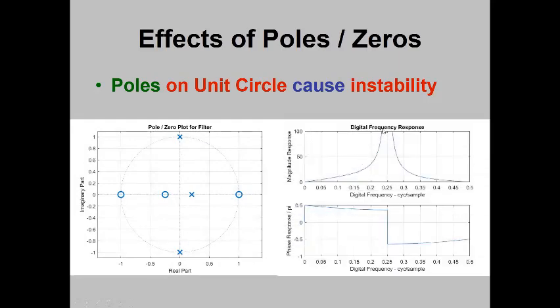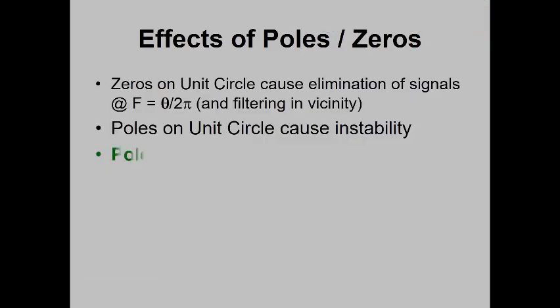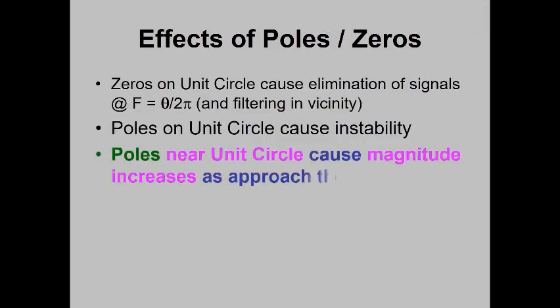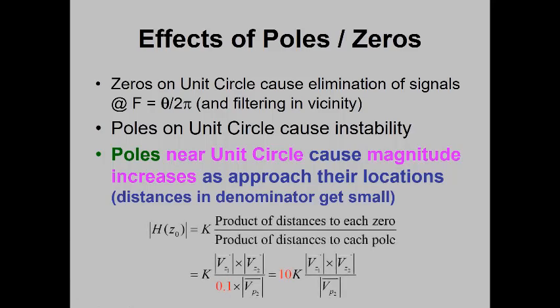We're going to get frequency responses that want to head off to infinity as we come around here because the rubber sheet's pushed up to infinity there as well. So not a good plan. We don't want to do that. And that's commensurate with when we looked at transfer functions and the requirements for stability. All of our poles had to be inside the unit circle for causal systems.